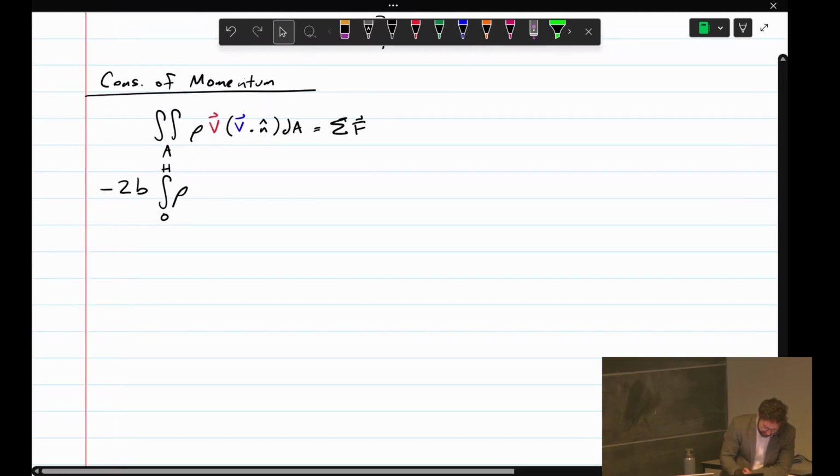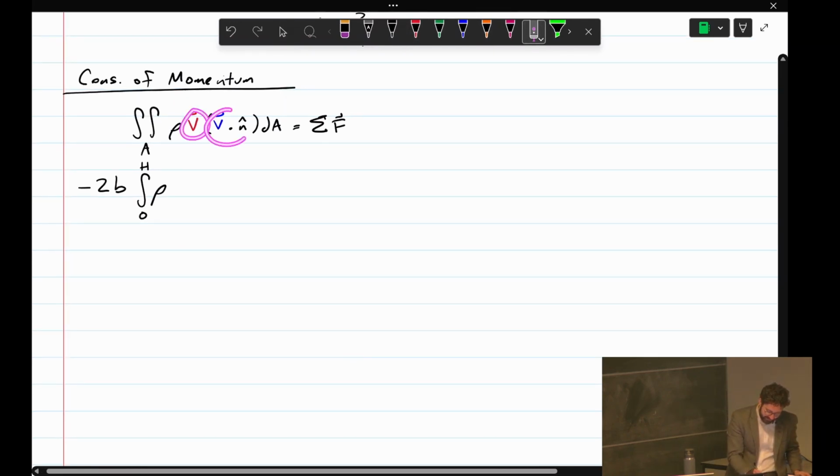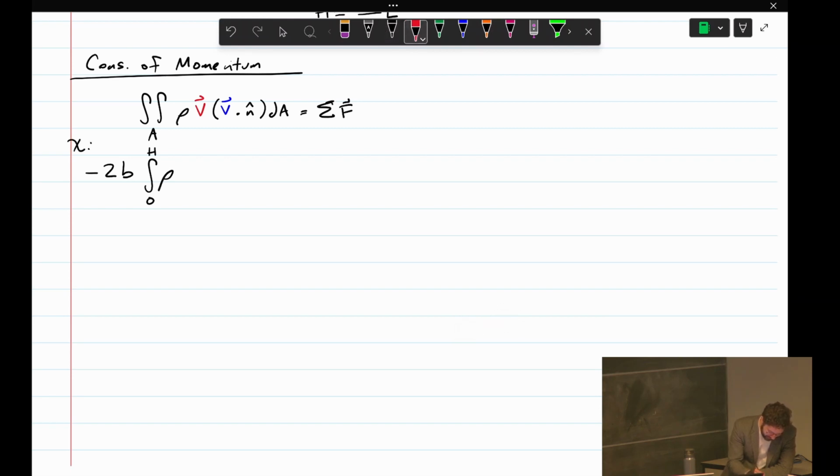if this looks confusing, once you work through this problem, you're going to see that it's not actually that bad. The one thing you will probably get tripped up by though is again the signs of things like this. So that's why I'm writing these in red. So we're going to do the x direction here. So the velocity in the x direction at face 1 is u0. And that v dot n is going to be negative u0. Again, we're doing dy1.